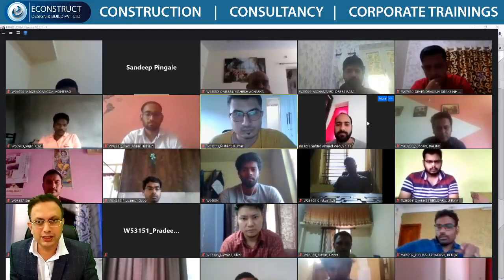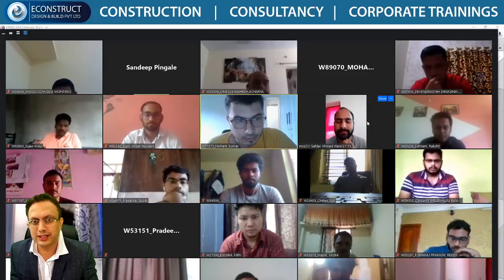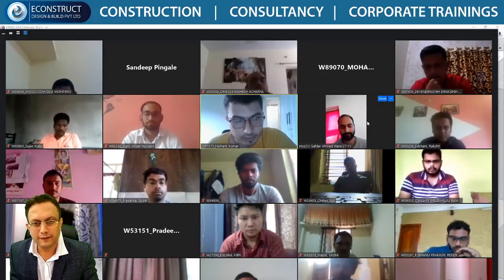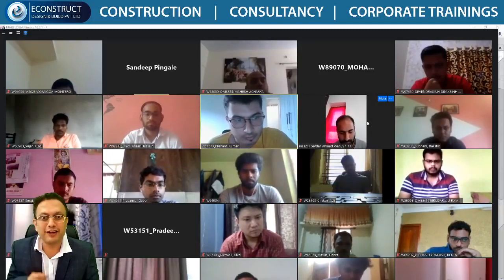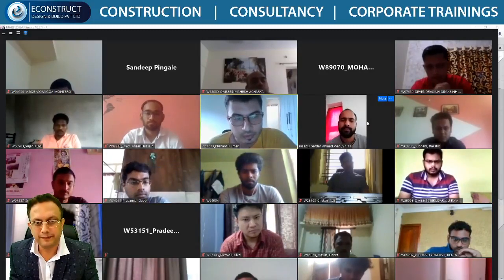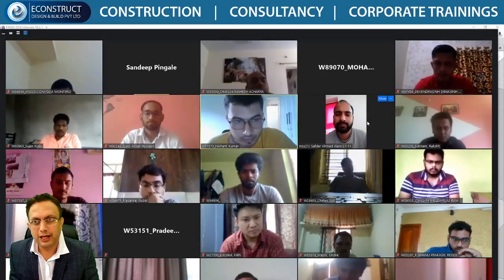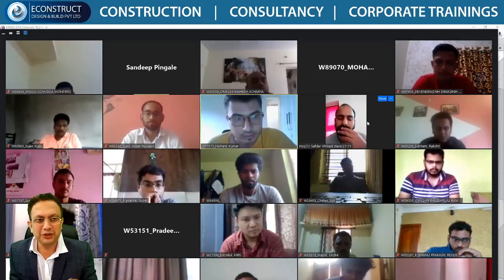Yes, any question, anybody? In case of sunken slabs in WC, do we need to give edge releases in the slab? Yes, it's preferred, because we have not given it till now. But how much that effect is coming, you can calculate it.